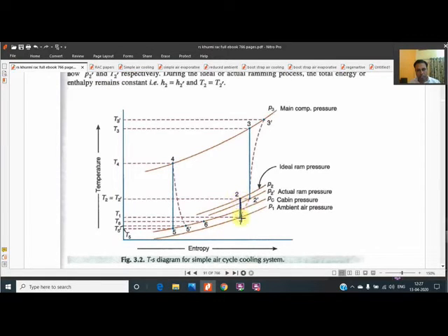It is initially compressed without any cost, because when we trap the air that is moving outside the aircraft, it automatically gets compressed, and thereafter it is compressed by an air compressor, and then after cooling and expansion to 1 bar pressure, because passengers sit in the cabin, that air is given to the passenger.